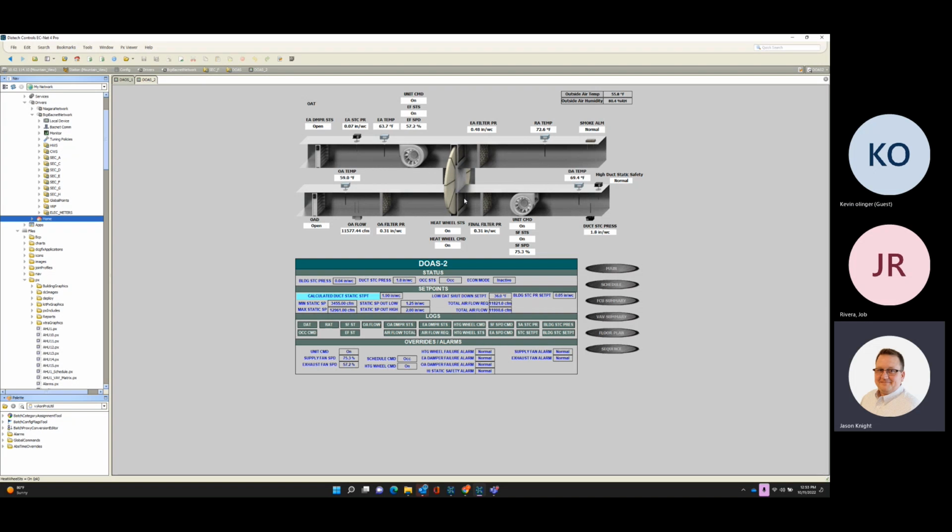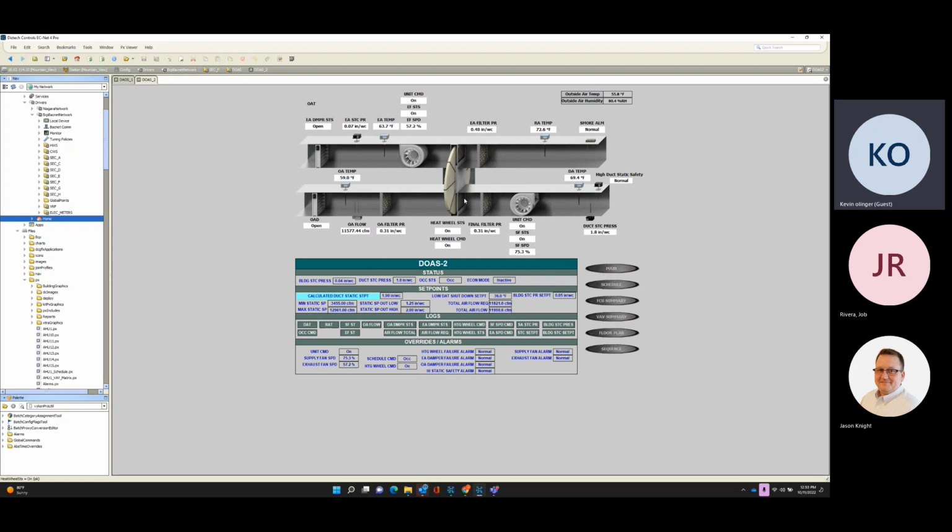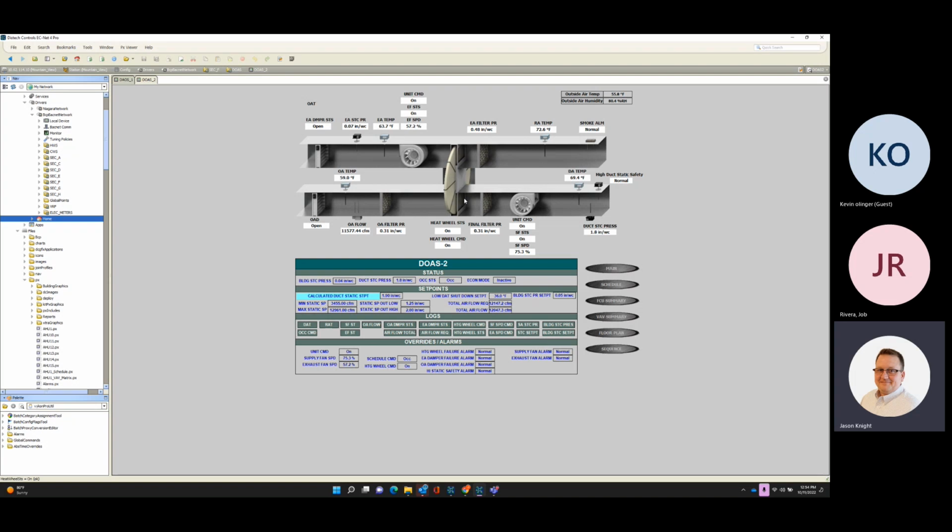That's a great question. I thought so. It is a great question because I don't have the set point on here. I want to say it's the economization mode. Yeah, so if the right here, sorry, I'm trying to jog my brain to remember. Econ mode is inactive. Whenever the economization mode is active, the wheel is off. When the econ mode is inactive, the wheel is on.